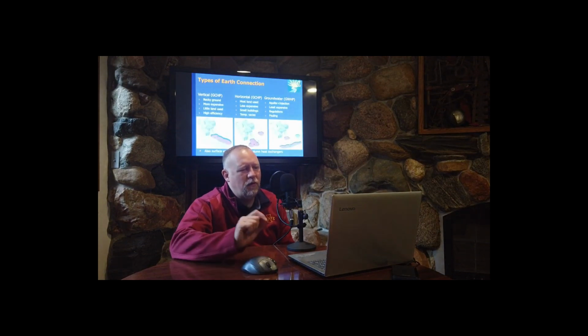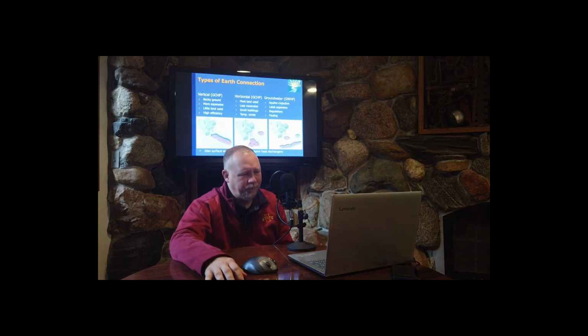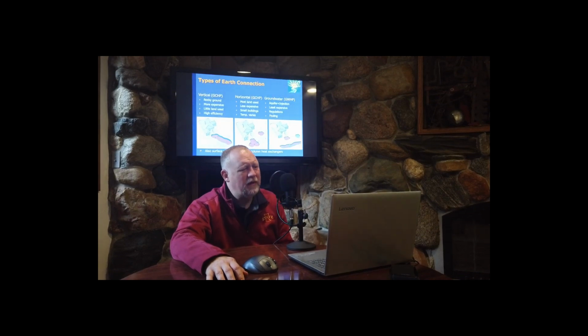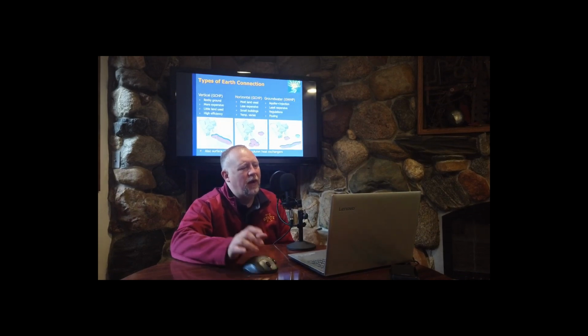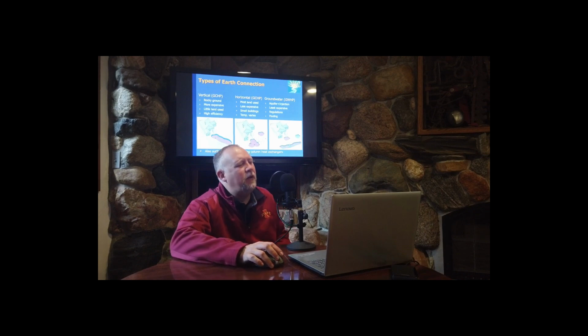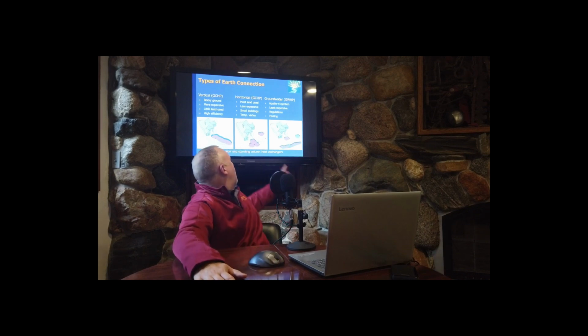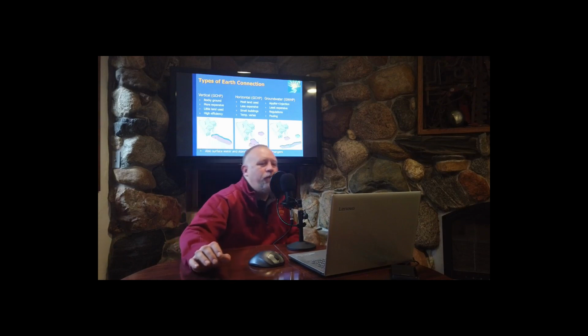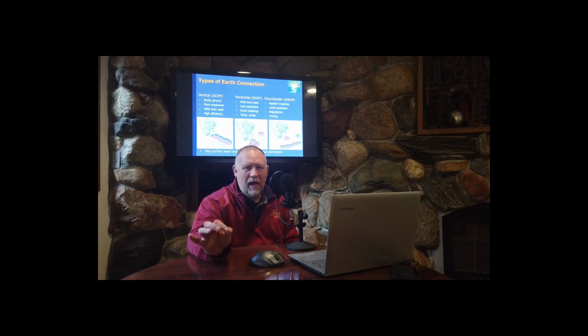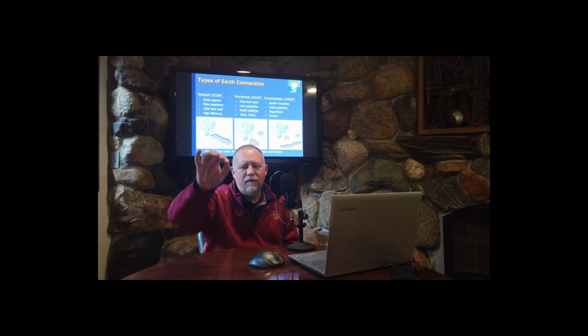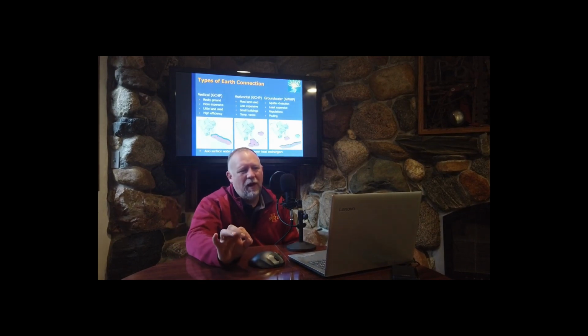Next, so three types of the earth connections. And one of these, the groundwater, I'm not going to talk about much because it's not really allowed in the state of Iowa or in most states. All right. Deep wells. They're going to go out and drill deep vertical wells in the ground, probably around 200 feet, maybe even deeper.